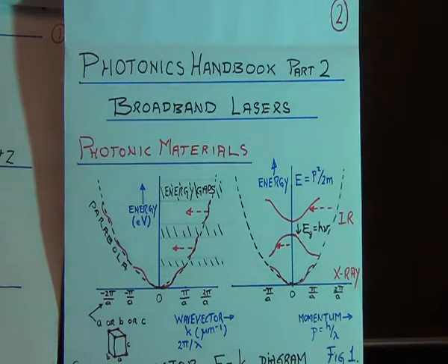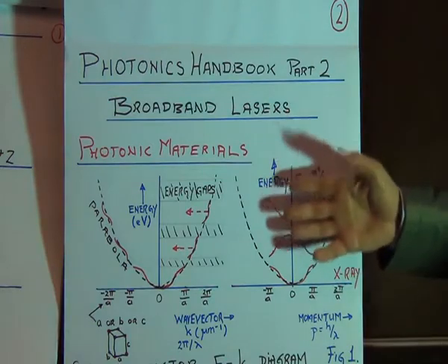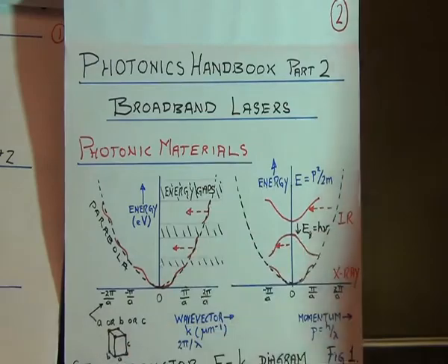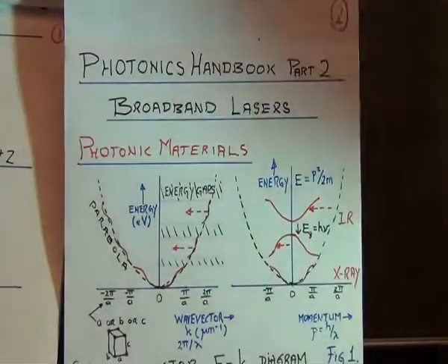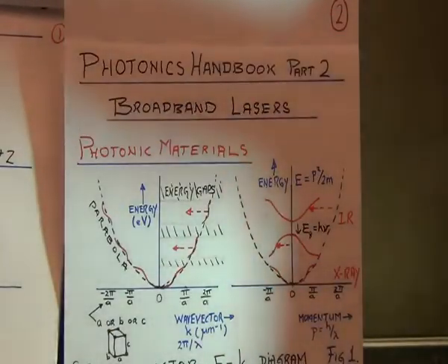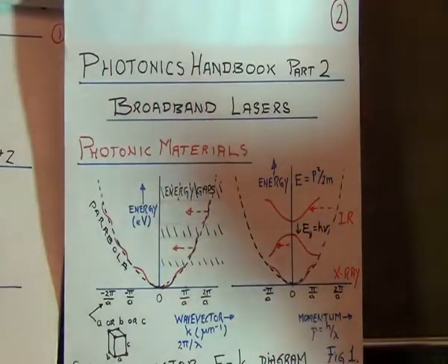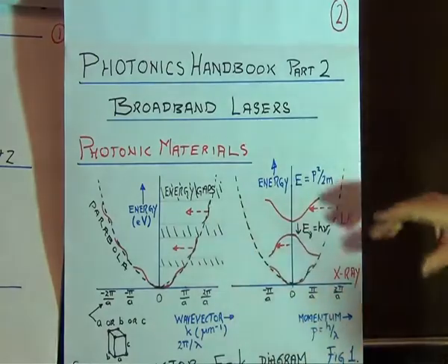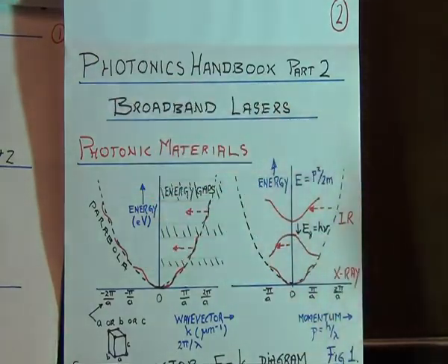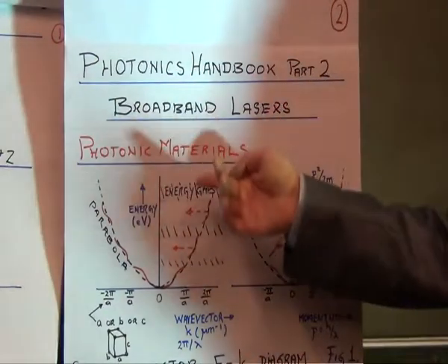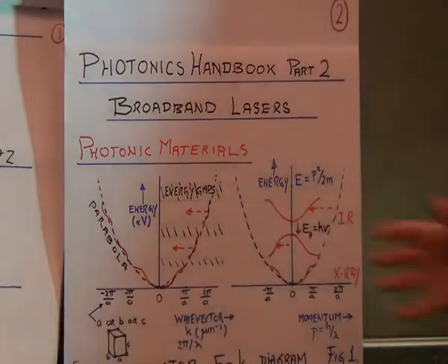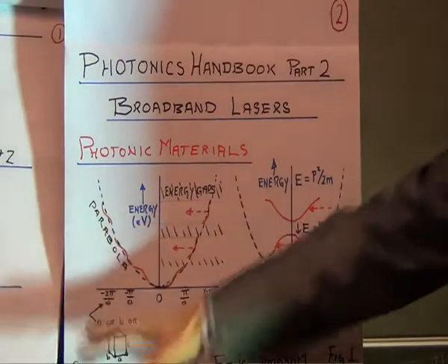Now, that's one way of compressing energy in the band diagram. Another way is to recall that these energy gaps are reasonable up here, but when you get down here, they're so big that it requires X-rays to access them. And we're not interested in that. In conventional electronics and indeed in photonics, we're only interested in the two upper bands. Right? We call them, as you know, the conduction band and the valence band. So eventually we'll dispense with all the lower bands.